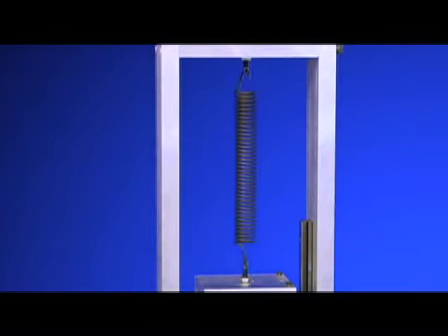And when something is linear in behavior, we call it ideal. So I model this as a pure and ideal spring. Now, the spring has mass. What gives me the right to neglect the mass of the spring? What gives me the right to neglect the damping, the energy dissipation in the cycling action of the spring?